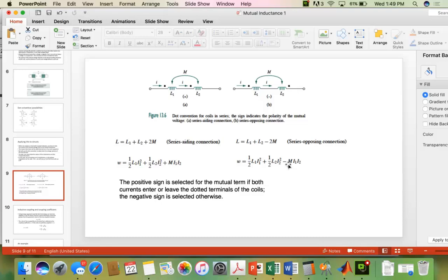That would only work if you had some local stray inductance and you wanted to try to get rid of that. Sometimes, just depending on the physical configuration, especially if it's a wound inductor, then you can do some things to optimize coupling the flux and wind something in an opposite way. But usually, just from a practical point of view, inductance that you don't want is typically not due to a nicely wound coil. So as a general rule, that would not really work.